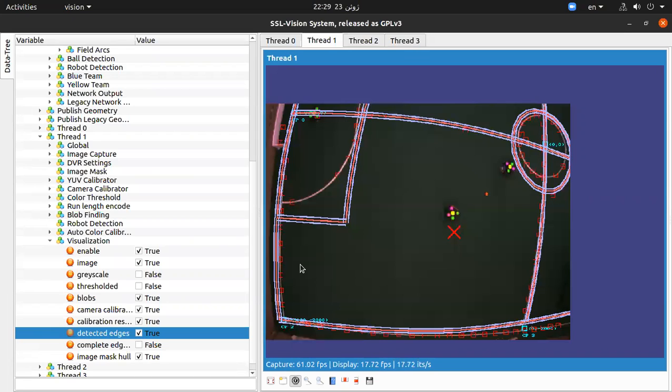But at least I would suggest that you measure the distances on the field and make some markings on the field where the new corners, the new middle line and the new touch line would cross, so that we can see it in SSL Vision, and can move the control points manually there and then do the calibration again.